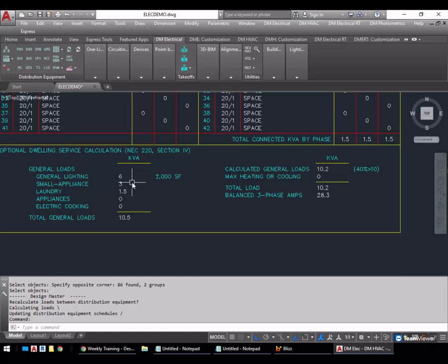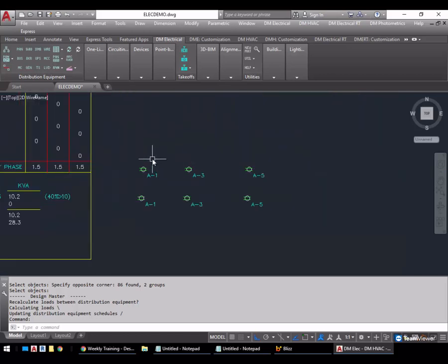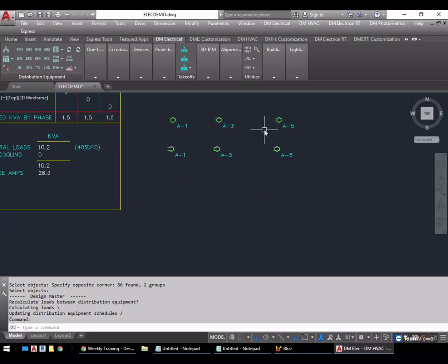And so then there's another question. How would you set up receptacles in the living spaces? So we've got our laundry room over here. We've got some small appliances over here in this room in my wonderful non-drawn building. So then we've got a living space here where we need to have some just receptacles. Now those receptacles end up in the general lighting load. So they're included in that 3 VA per square foot. So the question is, how do you handle all of that?